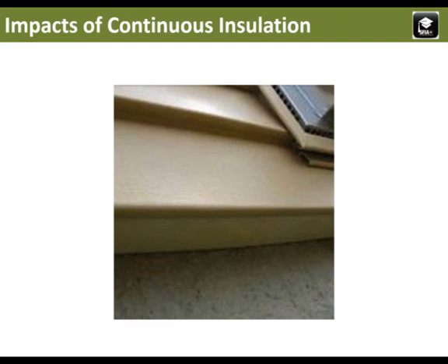This is probably a good time to talk about some of the challenges that continuous insulation poses for steel framing and buildings in general. The biggest challenge might be with fasteners. Although the fasteners are hidden in this picture, you can see the foam sheathing they have to penetrate to reach a solid surface for secure attachment.